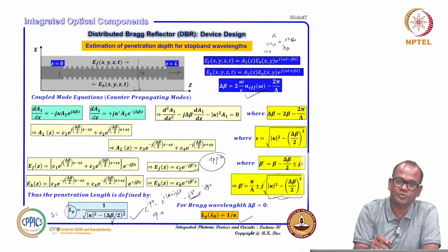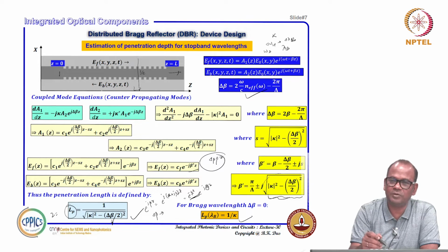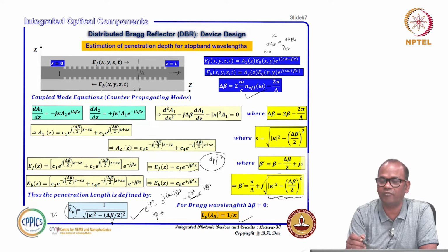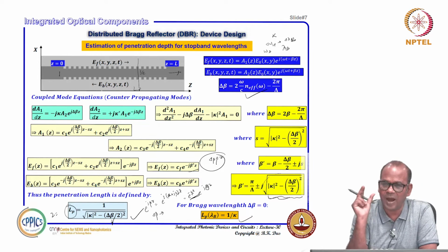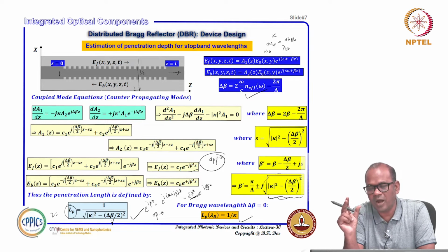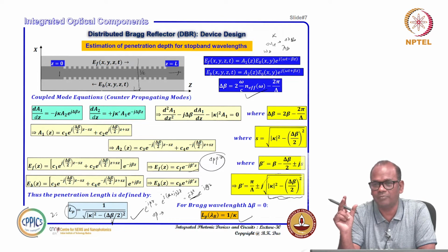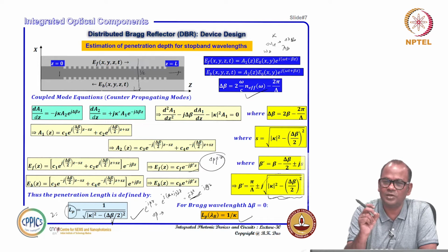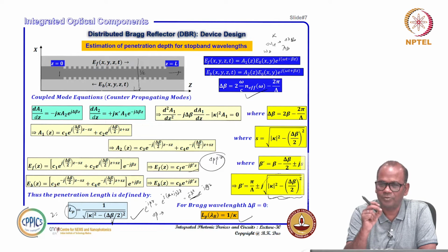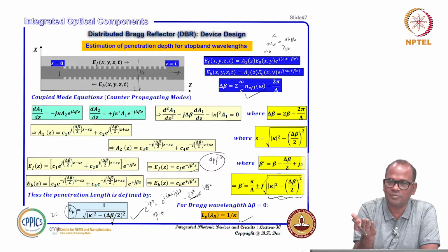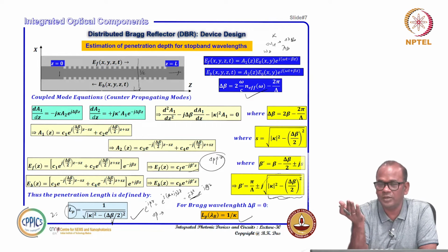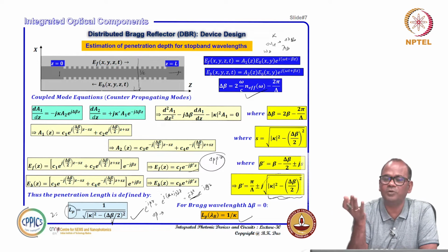Similarly here also, if I make some periodic perturbation in terms of dielectric constant or refractive index, then a certain band of energy around the Bragg wavelength will not be allowed. So, it is a band gap. Here also we have a periodicity, that is why it is a kind of crystal, but a photonic crystal. It is not a real crystal like the crystallographic structures we learned, but here also we get a crystal-like structure, in one dimension, and even in one dimension a guided mode with a certain band of frequencies will not be allowed, the stop band.